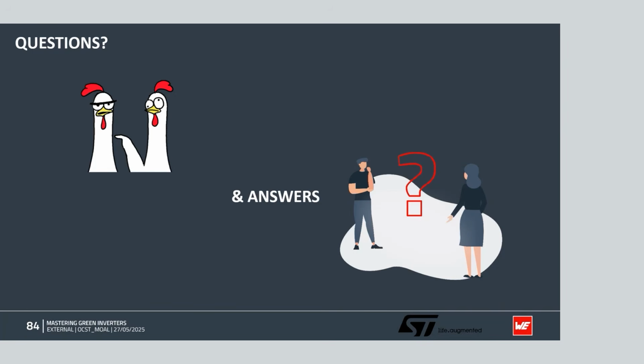That is where those Y caps were terminated to that chassis layer, which the heatsink was not connected to. So that's what we mean by connecting that directly to the same ground plane. Oh, that makes sense. Yeah, thank you. I hope this answers the question.